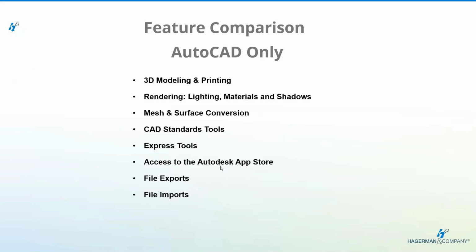When I was a CAD manager, this came in very handy for checking, especially new employees' work. I was able to look at it and it would compare the drawing to the CAD standards. I'd see if they were doing anything different than our company standards so that I could correct them early on. And usually once people learned our standards, they didn't get any messages from the standards tools unless they were doing something, because there's always something you may need to do outside the standard. So it's not going to handcuff you that much.